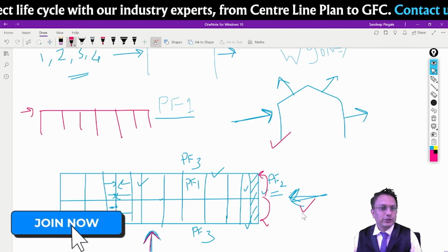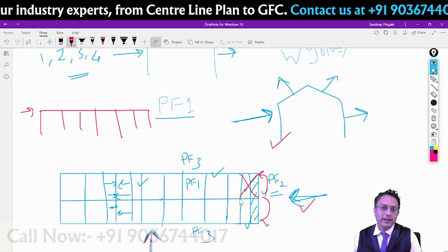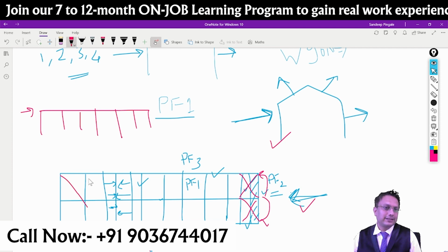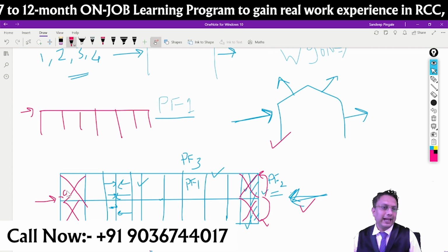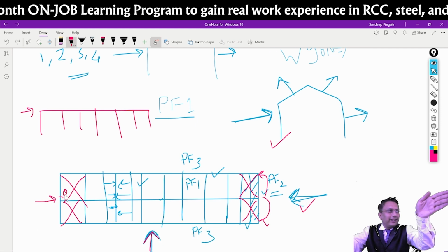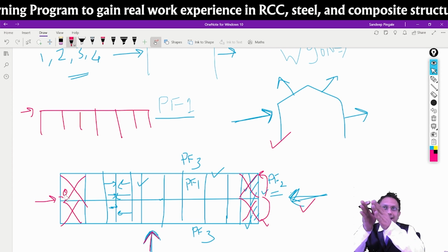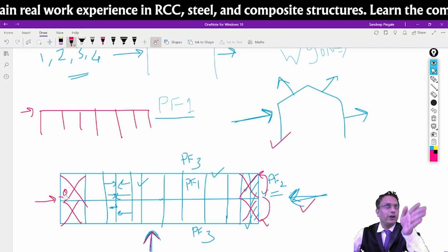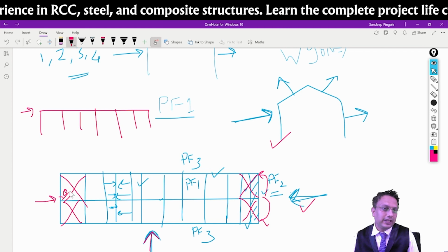Now, how the half is going to get converted is through the cross bracing. That we will see later on. Otherwise, in today's session, it would be too much. So whatever force is coming here will be distributed based on this angle theta. With sine theta and cos theta, based on that angle, the force will be there. That particular force will act on it, and with the truss analogy, it will go.